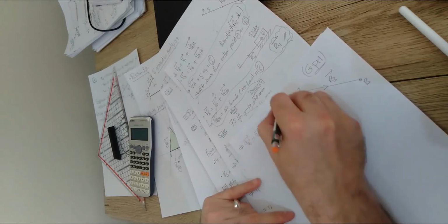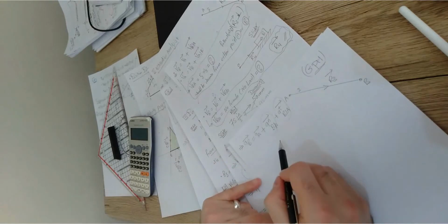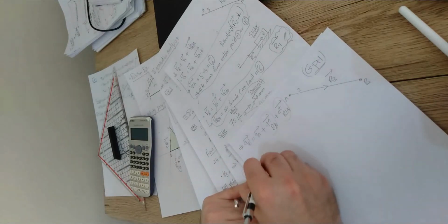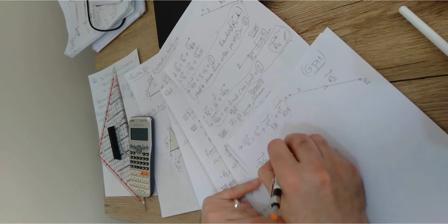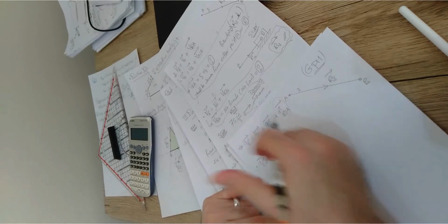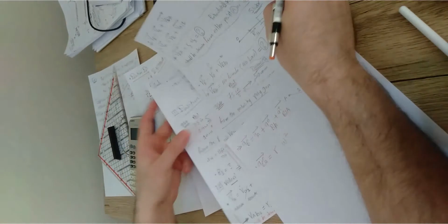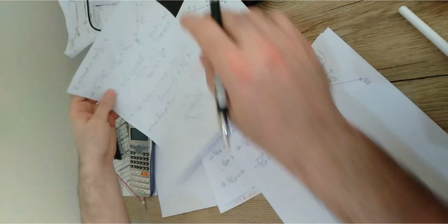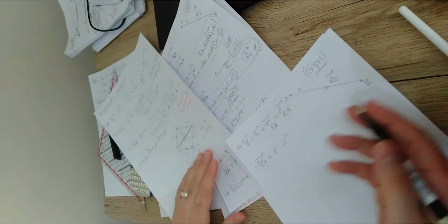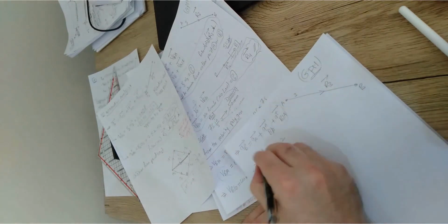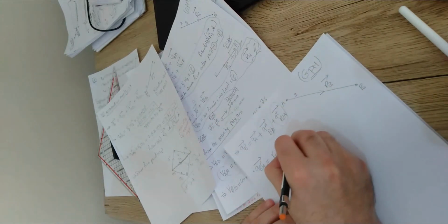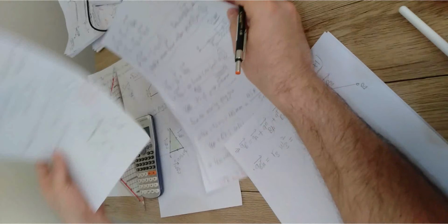And again, these are the two components that shall be joined. So the normal component, as we knew before from the dynamics or the complex algebraic method, should be R times omega squared, like what we did for the previous length. The normal component, for length 3, since we're already talking about length 3, should be R3 omega 3 squared.